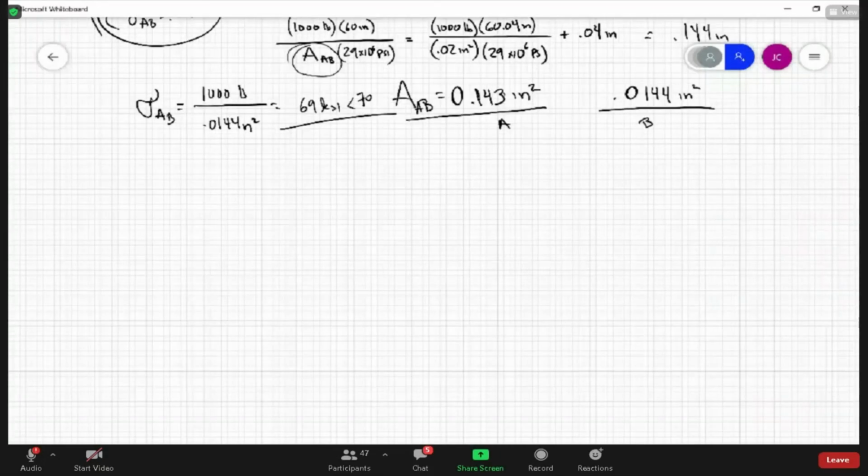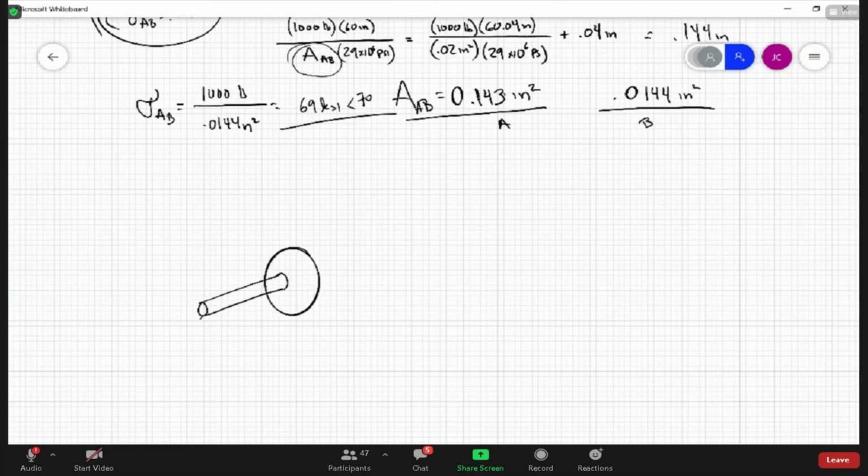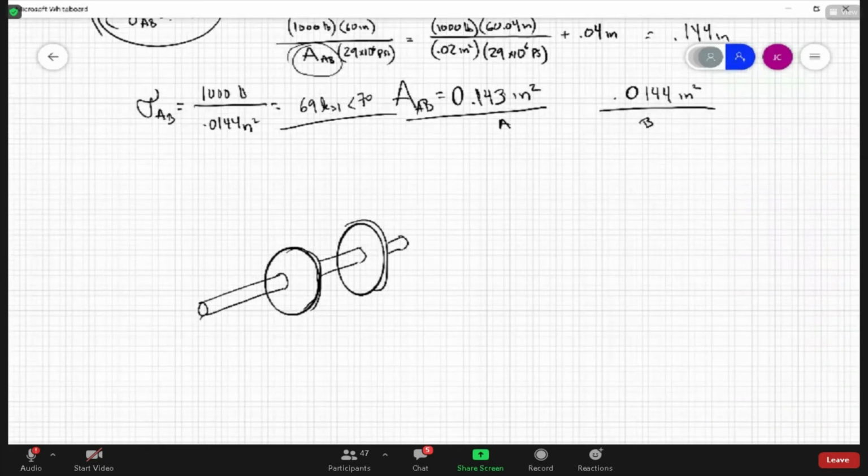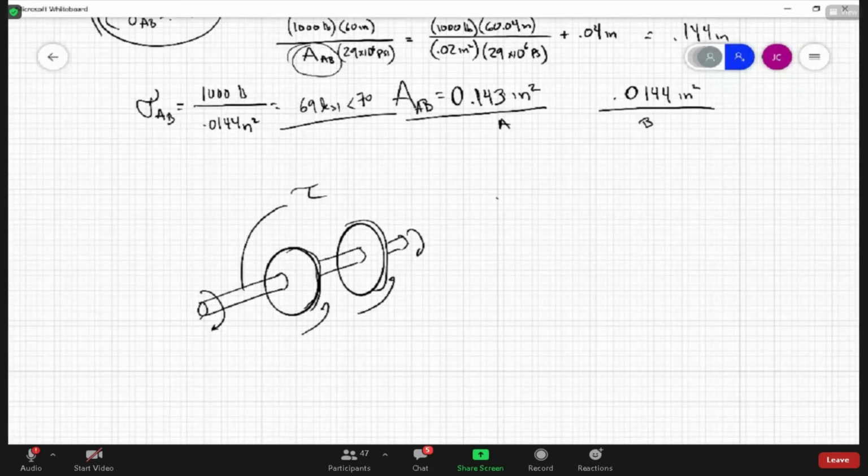Where you had, I forget which one that is. But that was an elongation. No, that was an angle of twist problem. But anyway, it would be a problem like that, where I give you the torque here, the torque here, the torque here, and the torque here. And I would ask you to find the shear stress in this segment, or possibly, it's a solid shaft, find the outer diameter given an allowable stress. Does that make sense? Things like that.